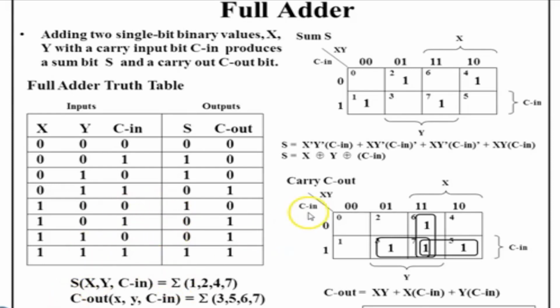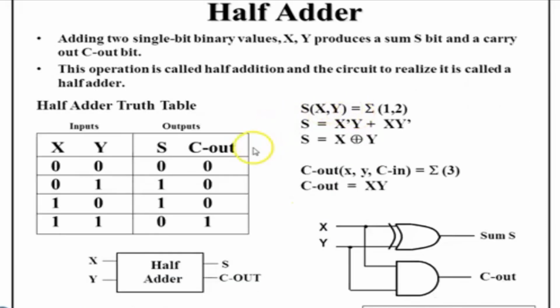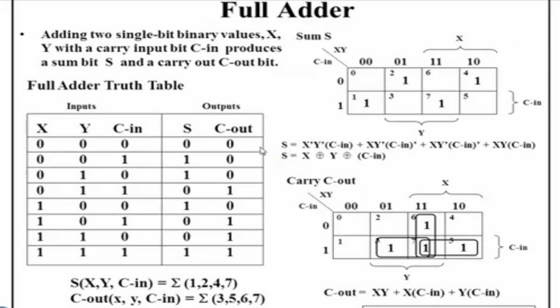So with the help of a K-map, it will be easier for us to draw the expression for a full adder. As we see in this, we have to use an 8-cell K-map as we have 3 inputs. So Cin against xy is drawn here, and we see alternate cells consisting of ones, right? So this is more like a chessboard. So I cannot group this one with any of the other ones to get a simplified expression. So each one of the ones in the cells is isolated.